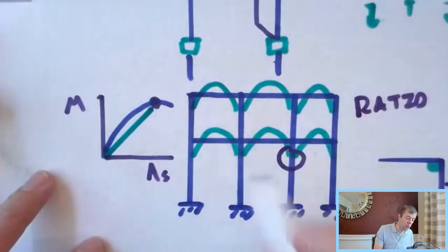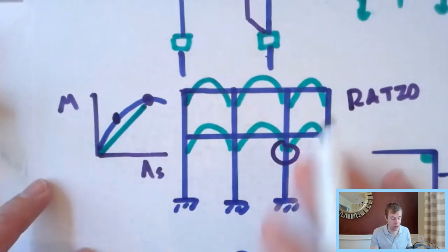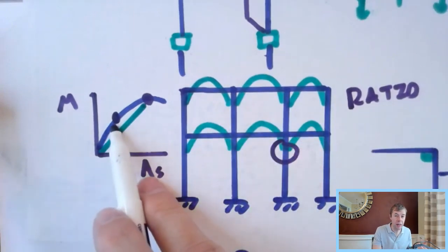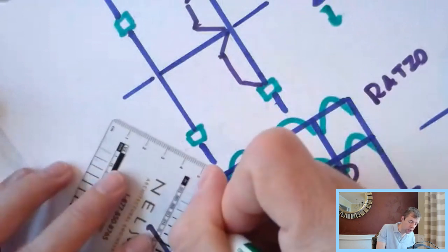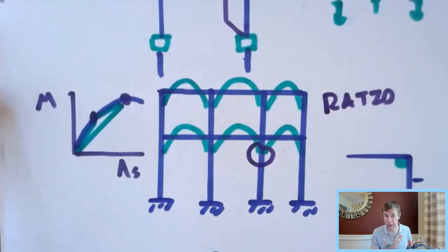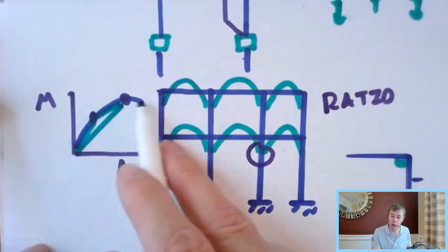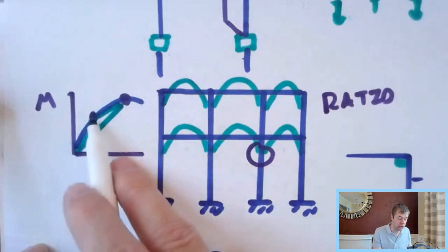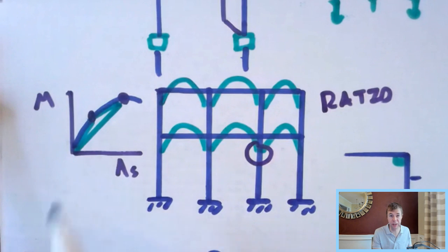If you say, oh, that's too conservative, I don't want to do that, then what you can do is solve for two beams. This would be maybe your highest moment in your entire structure, and this would maybe be your middle moment. And you could use two ratios, one from here to here, and one from here to here. For my project, since I'm trying to save you some time, I wouldn't do the second one. I would do the first one. But the idea is that if you take a parabola and reduce it into chords, single lines, you don't need very many points to do so, and that makes your designs way faster and way easier. That's extremely powerful.